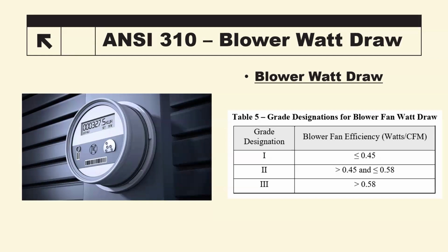And as I said a second ago, and I'll reiterate it again, this is a light bulb moment. Why would watts be higher? Why would we get a difference in the range of how much power is being drawn? If you go full circle, it's ductwork compromises. It's like when you take blood pressure and it's high: possibly you have some sort of blockage somewhere in the system, or constriction of the blood flow. Same thing with ducts. You've got a constriction because it's crushed, it's kinked, it's got sharp bends to it. It's just not following manufacturer's installation instructions.